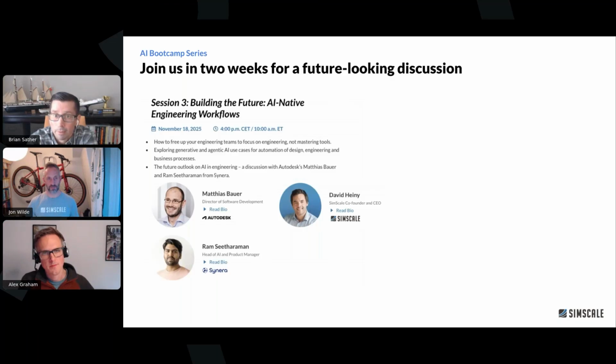You want me to answer that? I would say you'd want to include the variables that you believe are going to have an impact on the resulting performance that you're interested in. And yes, you would want to run a DOE that characterizes the extent of the design space that you'd be interested in exploring in the future. Okay. Yeah, I would say the same. If you have 6 or 7 different features changing, you might need more than 200 simulations.